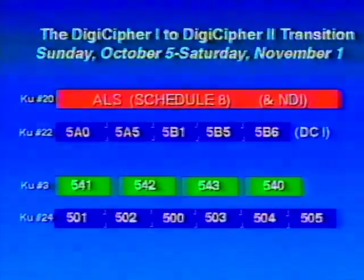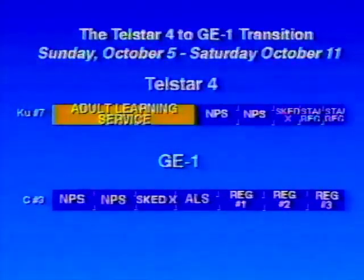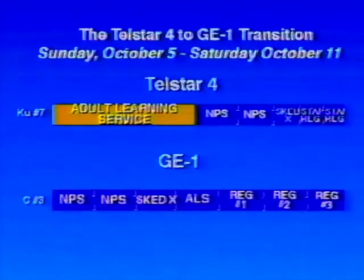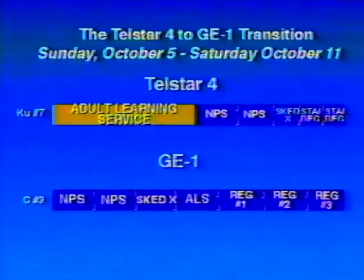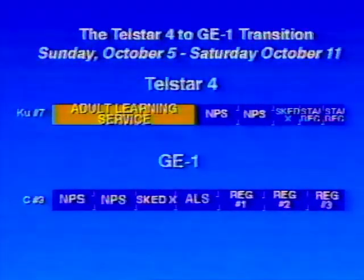Also, now talking about the Telstar 4 to GE1 transition, remember on Telstar 4 you're looking at that 5-channel Digicipher 1 MCPC and ALS analog. On GE1 you go straight to a 7-channel Digicipher II MCPC with 4 PBS schedules and 3 station and regional network turnarounds. Those regional network turnarounds are exactly analogous to the 3 SCPC channels on GE3. They do not equate to 5B5 and 5B6.